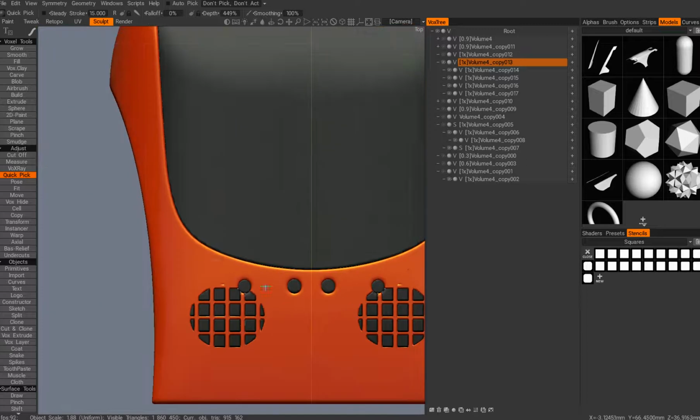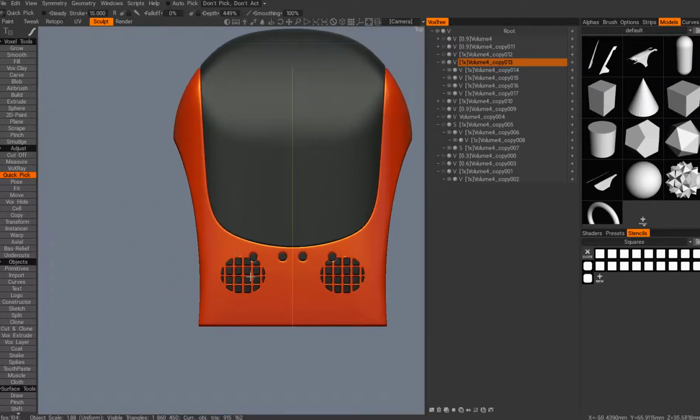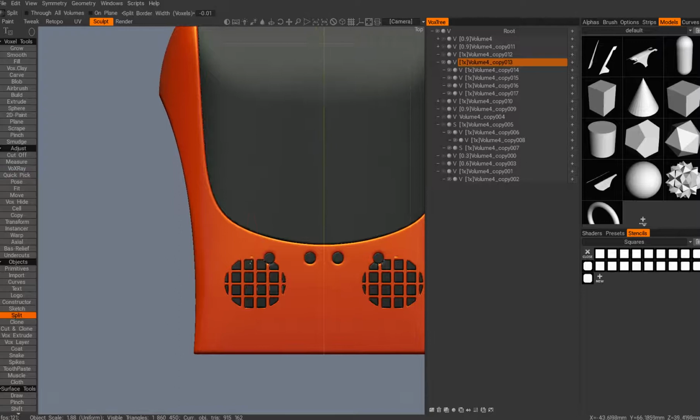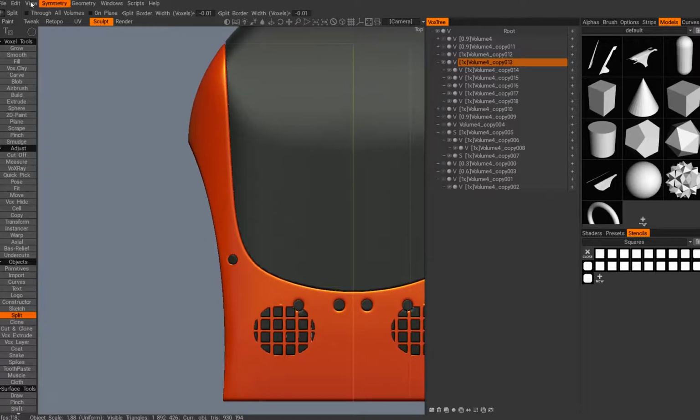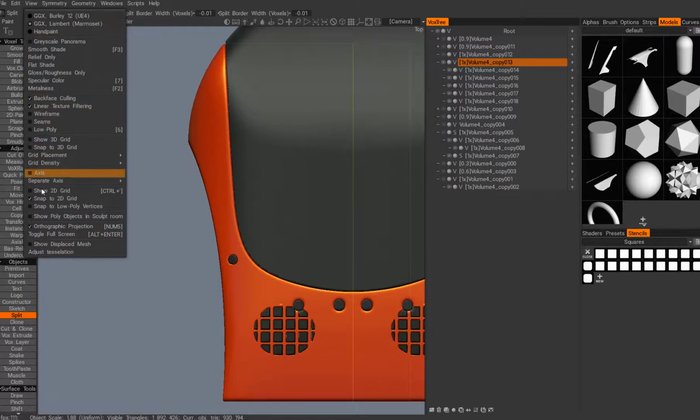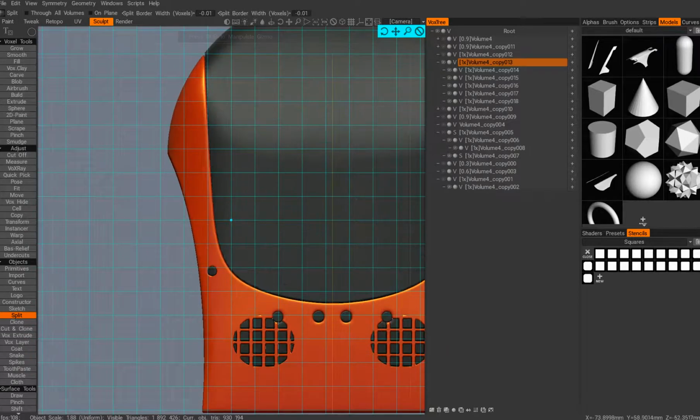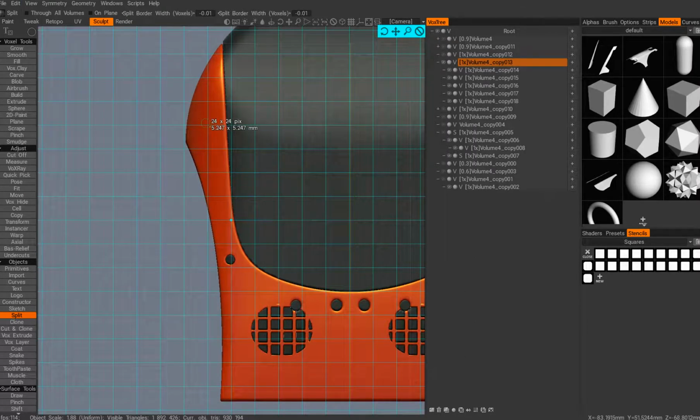So if I'm just doing some bolts around, I would be using the split circles tool, and I might turn on the grid, maybe I'll turn off the snapping on the grid, but I'll put a 24 pixel bolt right here, and then I'll move 1 2 3 4 5, put another one, I'll move 1 2 3 4 5, I'll put another one.